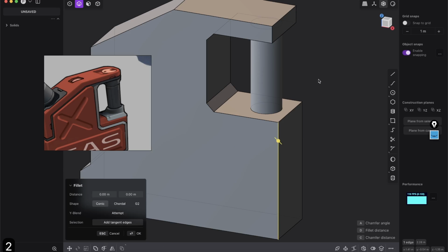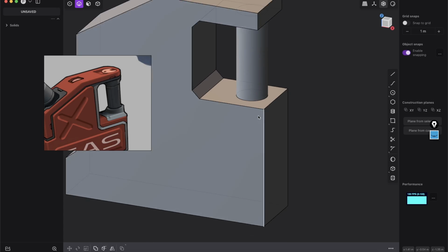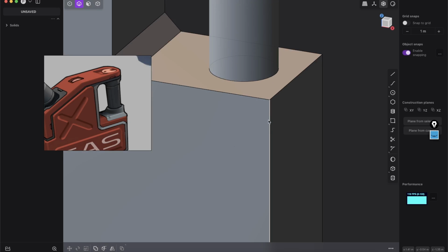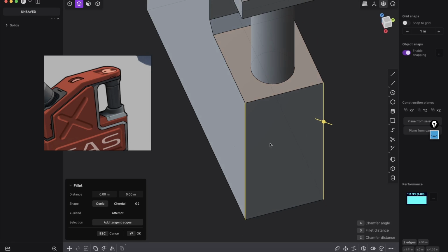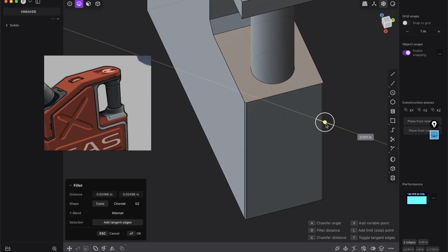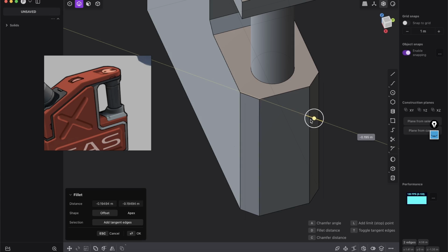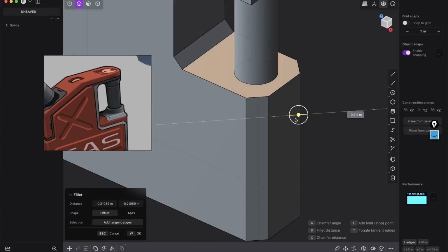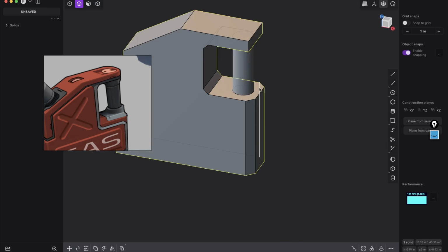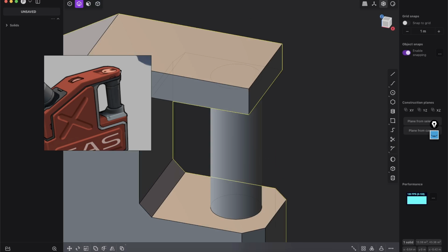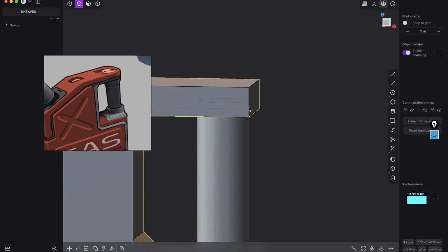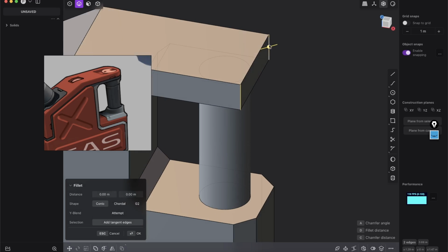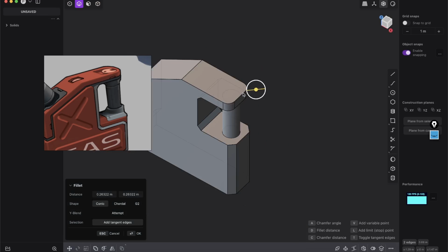And again in edge mode, I want to give just a chamfer. So in edge mode, I will select this edge, shift this edge, and again we have this yellow symbol, which we can then drag either in the chamfer or the fillet direction. And I just want to do something like that. And here at the top, I just want a little bit of a variation. So again, I will just select this edge and shift click this edge, but here I just want to give a little bit of fillet.